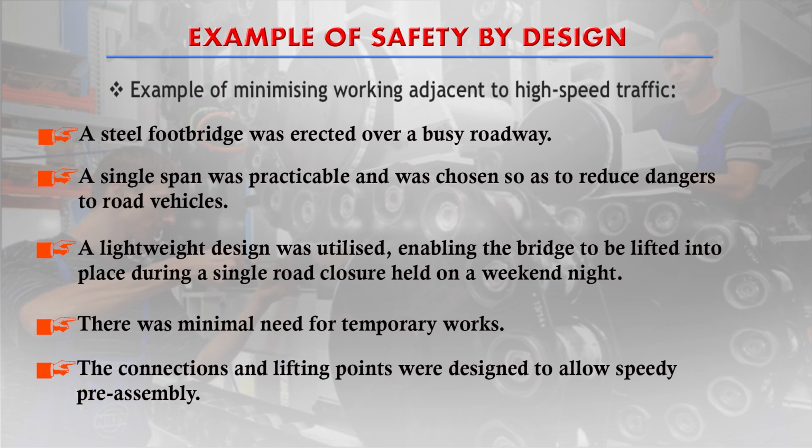The connections and lifting points were designed to allow speedy pre-assembly, because ready to use assemblies are available. If we are doing the welding and other structures are designed for erection of the footbridge, then it will require more time. But if pre-assembly is already there, then it will be speedy, therefore it will minimize the total hours of working for erection of the bridge.